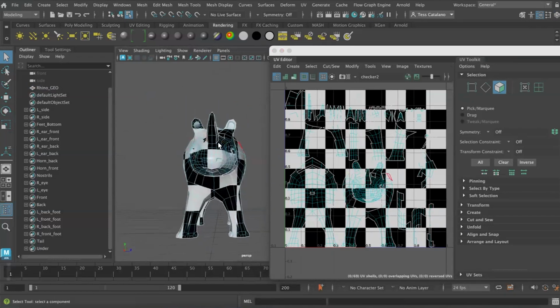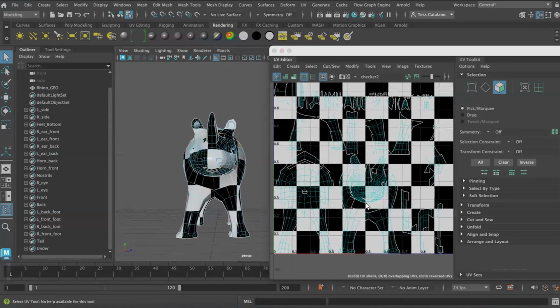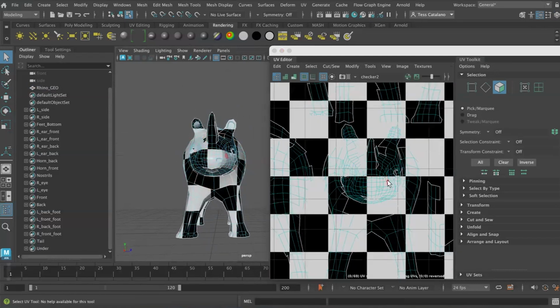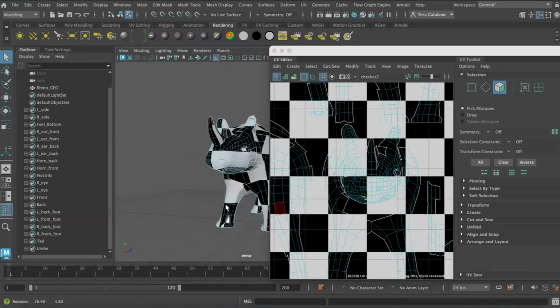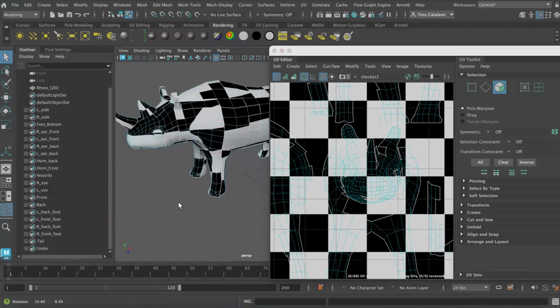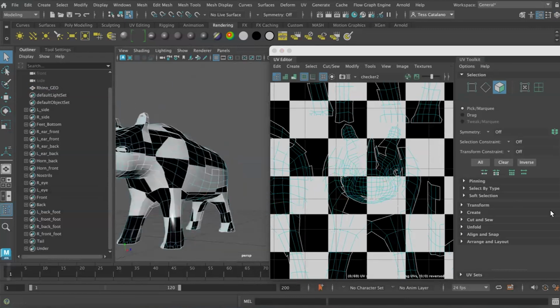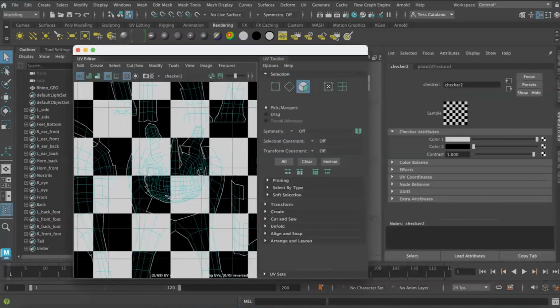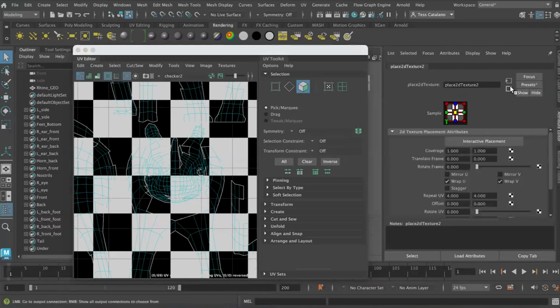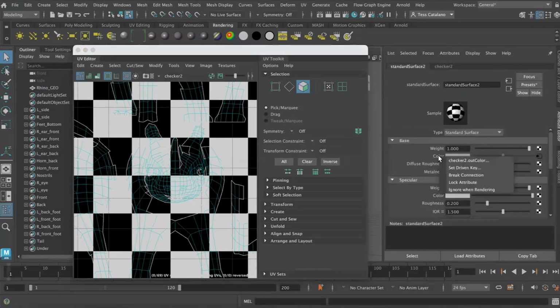There's a little bit in the front, and you can see where that is placed here, and that's why this is tiled the way it is. So maybe it's okay, but it's rather imperfect. Let me go back to my texture, my material node, and break that connection again.